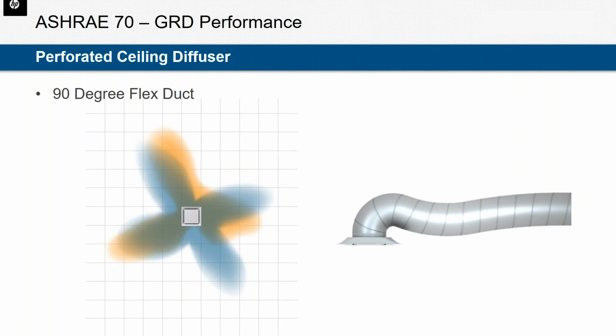Now, again, this isn't going to say that all flex duct does this, but if you're using flex duct, we really recommend you have some structure to it that has a large enough radius in the bend. And if you can, use one of those devices that kind of structure the elbow. That way it doesn't create a tight 90-degree bend, but a longer radius.